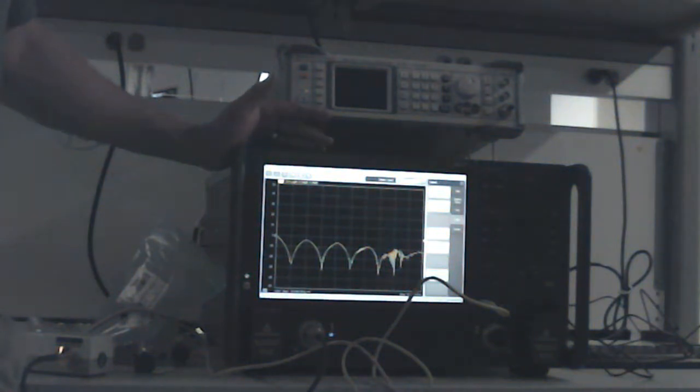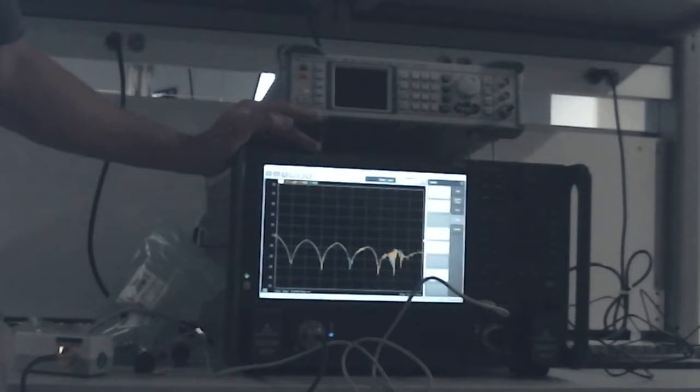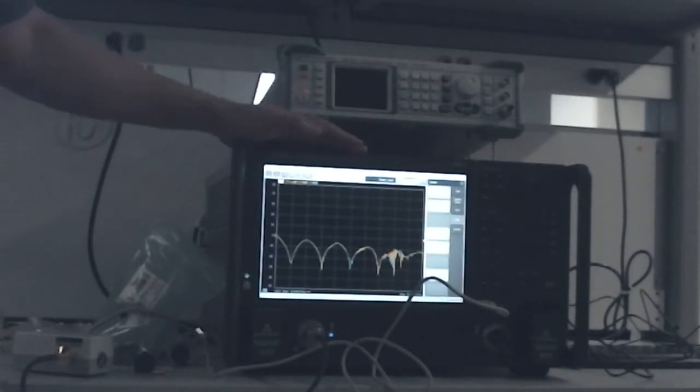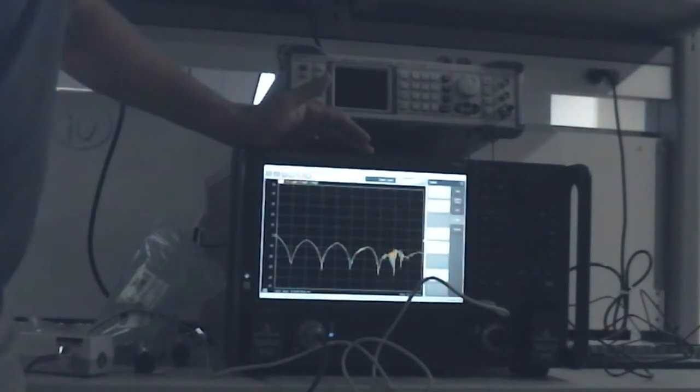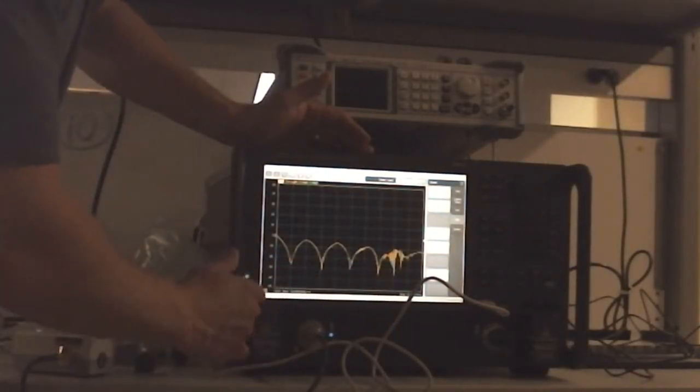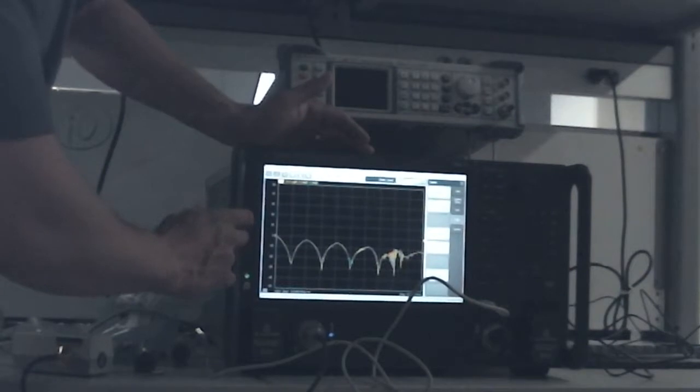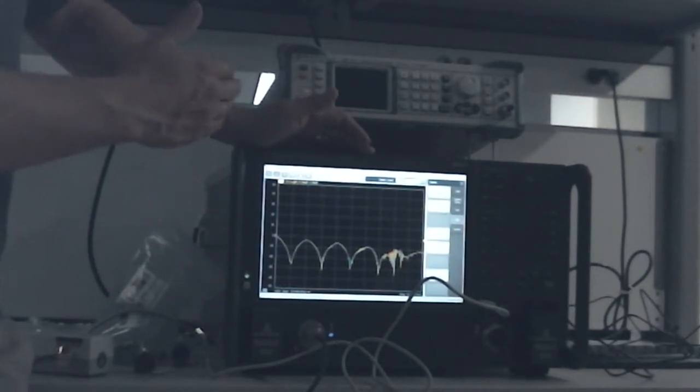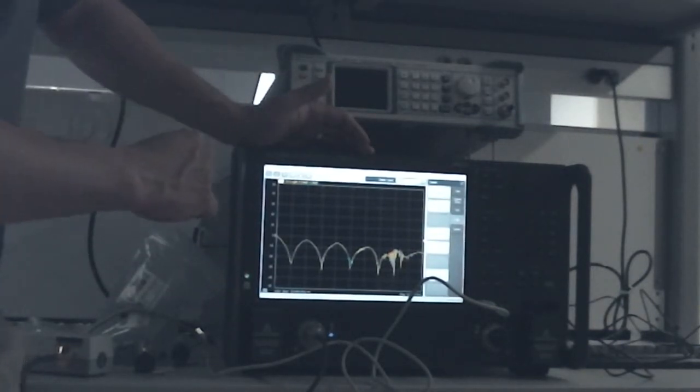So for you guys, I think since you're doing the maximum? What's the maximum power? Depends on frequency, right? So you can easily get, I'd say, probably around plus 13 for the full range. At the low end you might be a little bit more limited. So if you're going below 100 megahertz, that's where you might start running into issues.